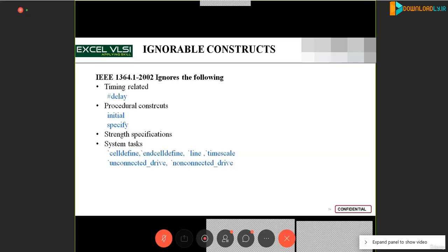So that is where, when you're designing, you should be very careful, especially when you're writing RTL, register transfer logic. When you are writing a test bench in order to test, that is okay. You are not converting it into hardware, it is just behavioral code.